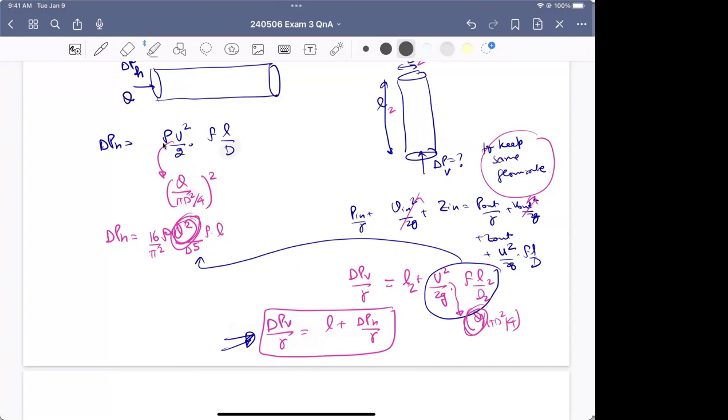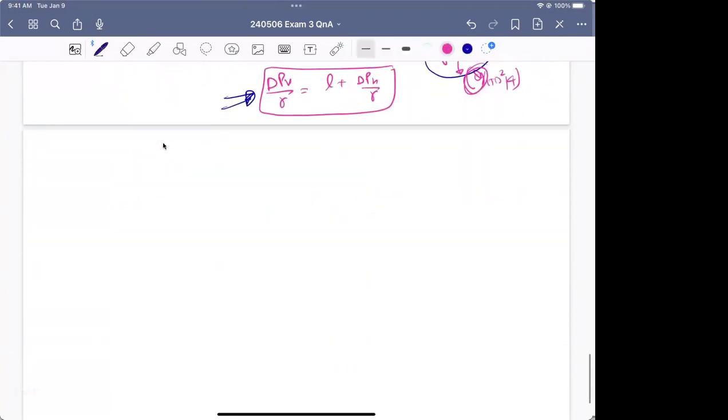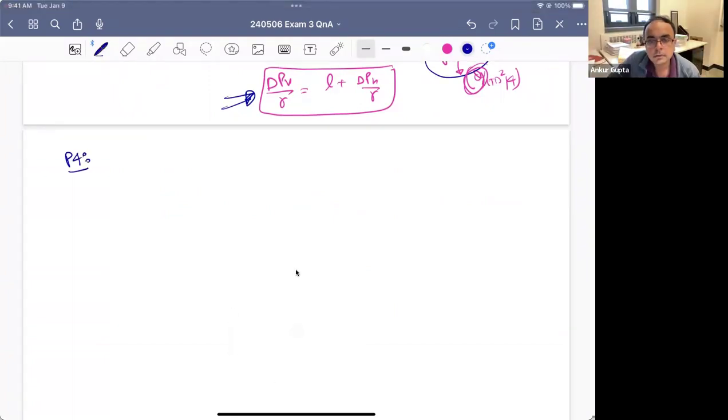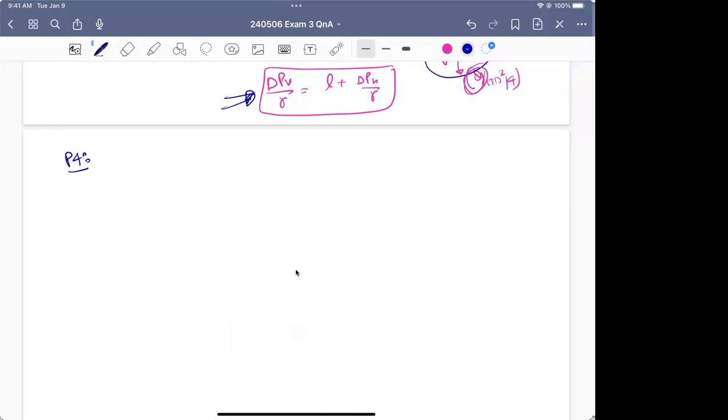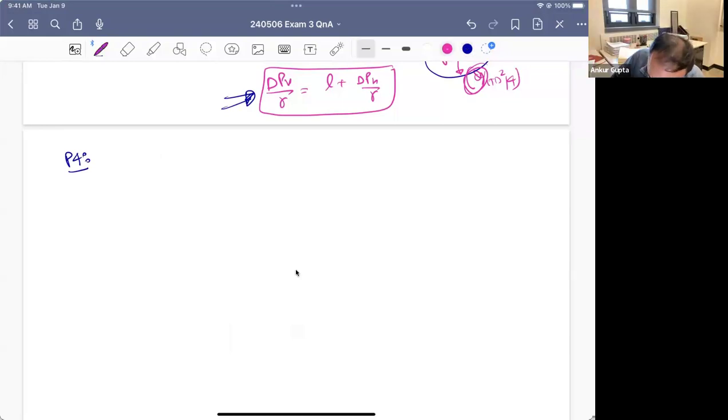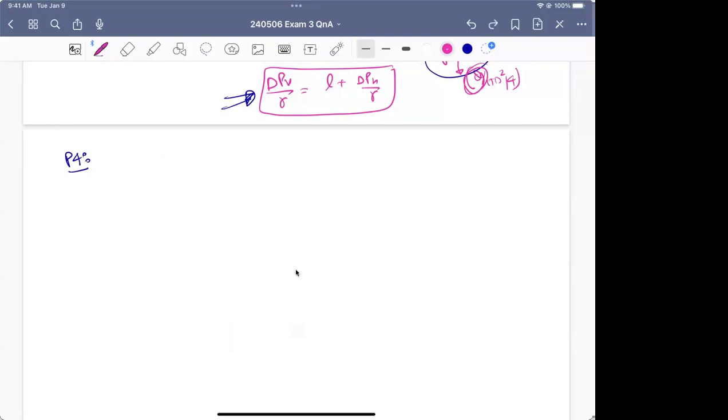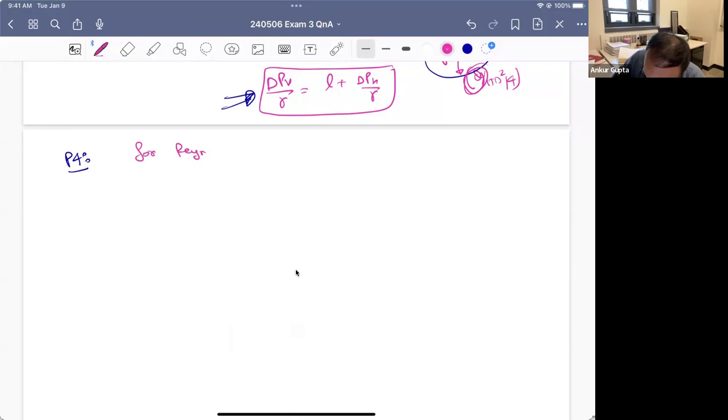For question 4, when we check the Reynolds number to know if the conditions apply or not, how can I know which density or viscosity I should use? The water or the air, or the object? So for Reynolds number, always make sure to use the density and viscosity of the fluid in which the object is moving.